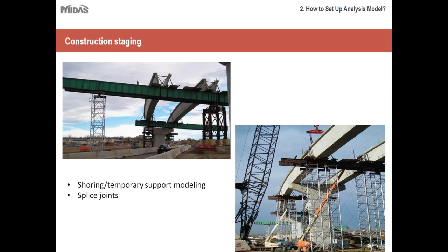Instead of just applying a point support and getting the camber value for the superstructure, you would have to model the entire system underneath it, something like this, and then assess the forces.